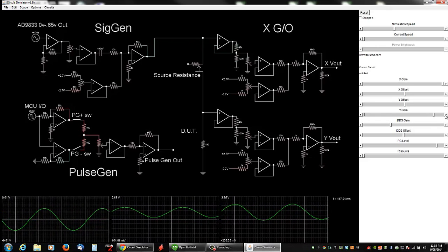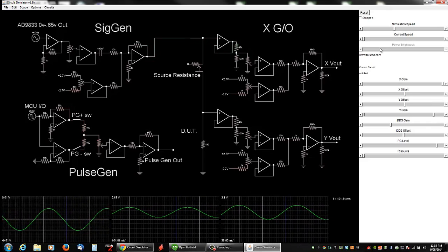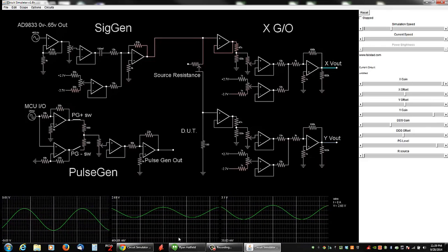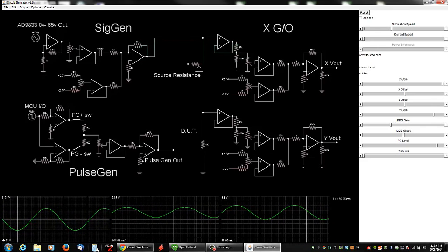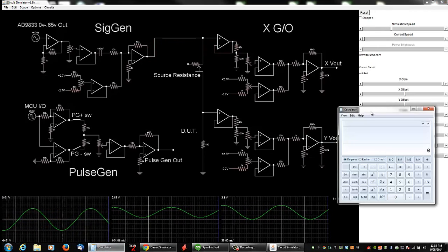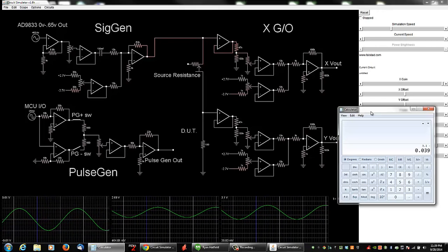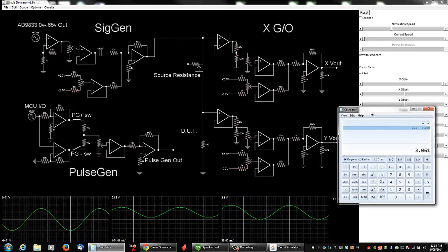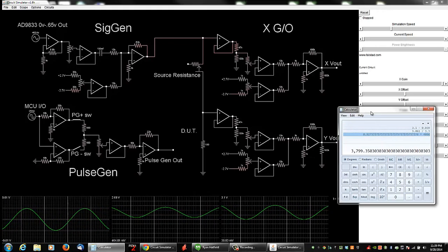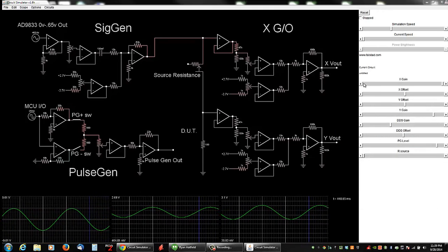Turn the gain back down. Okay, looks like in this case I'm only going to get 38 millivolts up to 3.1. 3.1 minus, we'll call it 39, 3.061 volts out of 3.3 on a 12-bit ADC is going to give me 3,799 counts. That's plenty to work with.